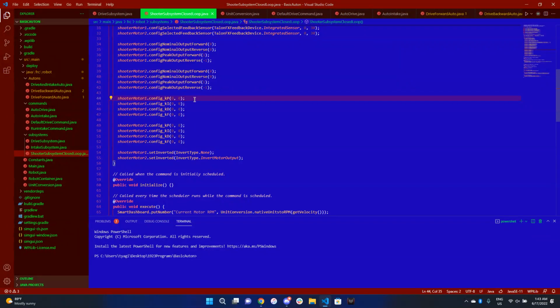Okay, hopefully you tried it. So this one here is 0.275. We do have an I term at 0.00012. Our D term is 0.1, and our feed forward term is 0.03. And it's the same for these guys as well. It's all the exact same.